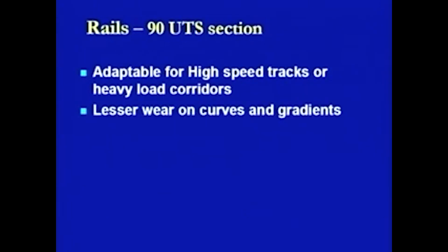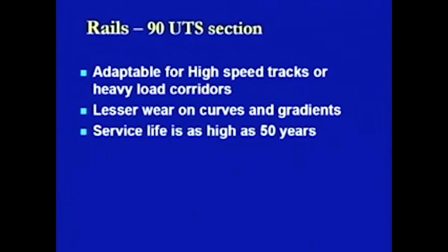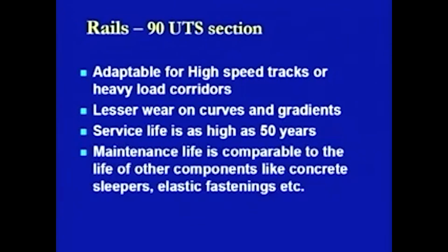They have a lesser wear on curves and gradients. This lesser wear is related directly to the hardness number, as we have seen. It has a higher hardness number as compared to the conventional systems. And obviously, service life, as we have seen previously, is as high as 50 years. Maintenance life is comparable to the life of other components like concrete sleepers, elastic fastenings, etc.